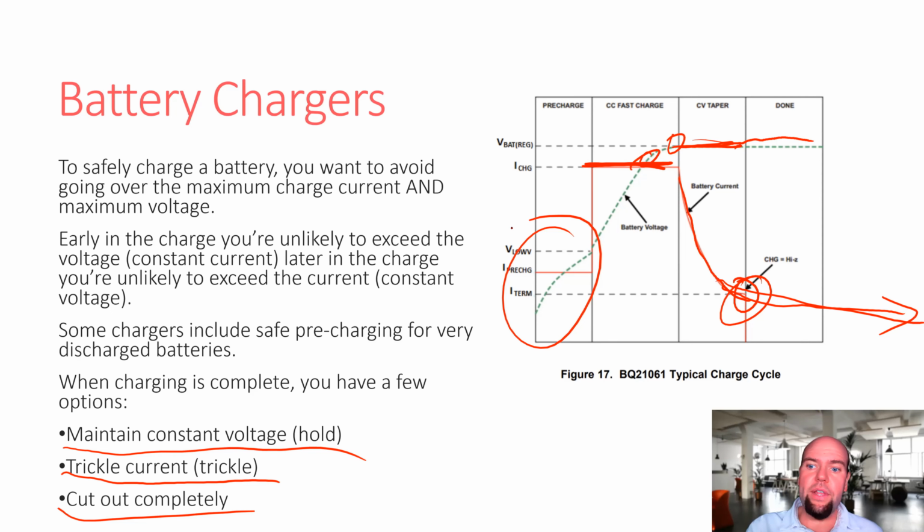This is not good that you let the battery drop all the way down. So as we charge it back up, as we get it back to this sort of bare minimum operating voltage, we're going to do it slowly. Some of them will have this pre-charge current, where they do a pre-charge at a low current until the battery gets up to a level of charge that's the minimum that you should discharge the battery to. Once we get up to that, then we go back to the normal charging mode.